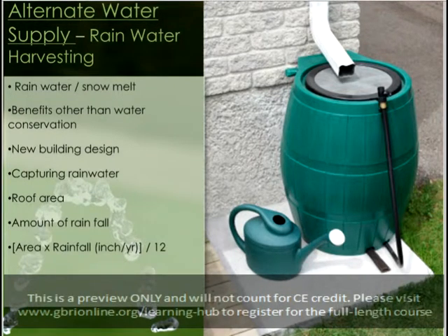The size of the cistern should be decided based on peak rainfall during one or multiple years, the amount of time between rainfalls, and irrigation demand. The link on this slide will take you to one of the various rainfall calculators found on the internet. If projects utilize rainwater for indoor water applications, such as flushing toilets or urinals, it will contribute towards indoor water use reduction credits as well.